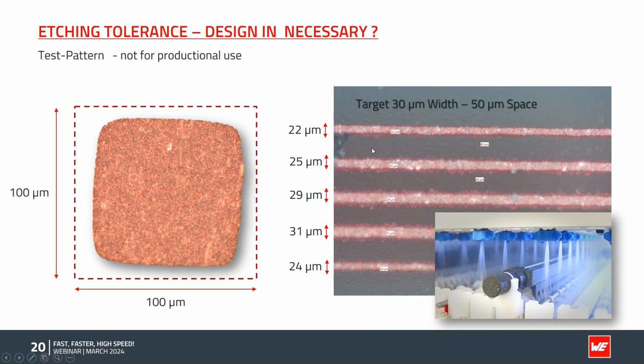This is line specific. So in the etching line, we know these values, we can fine-tune it, we can modify the track beforehand, and we really get very close to the target. But again, we need to know what your target, what your expectation is. Therefore, some discussion about this topic is needed before we start production.